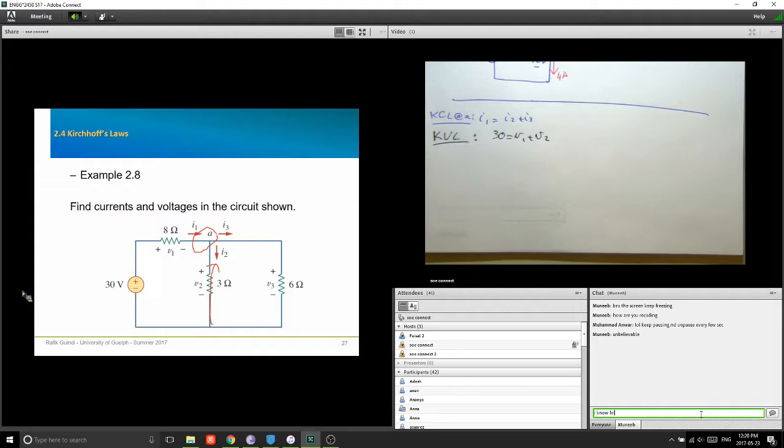And then I'm going to go around like this. Is that a rise or a drop? It's a drop, okay? So this rise, V2, is equal to this drop, V3, and therefore you get one more equation. The third equation, V2 equals V3. Okay? Now, you still need to use Ohm's law, and let's do that.